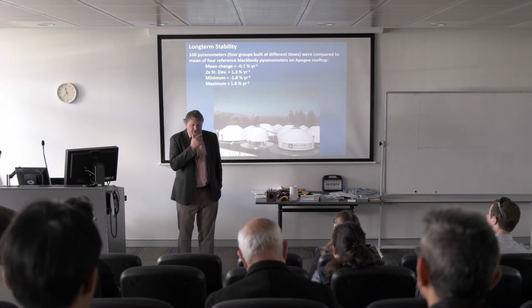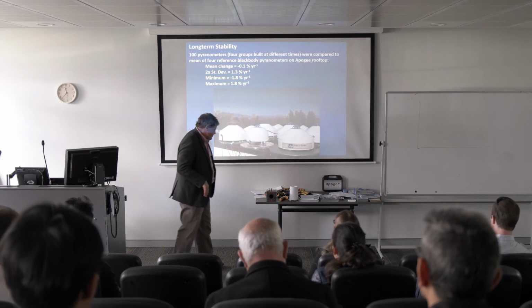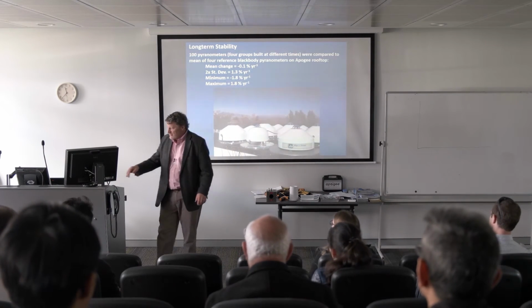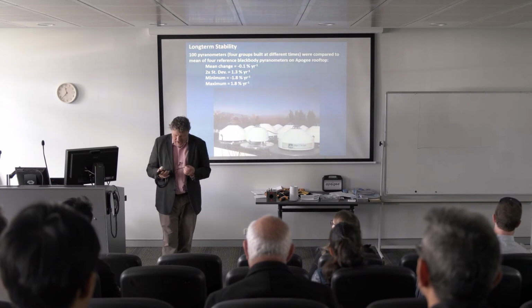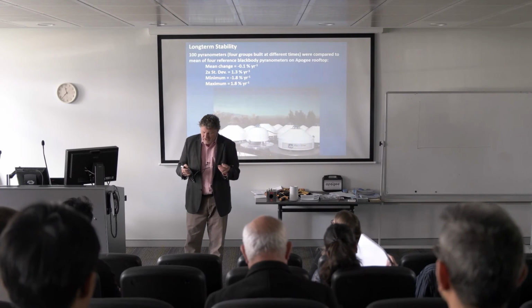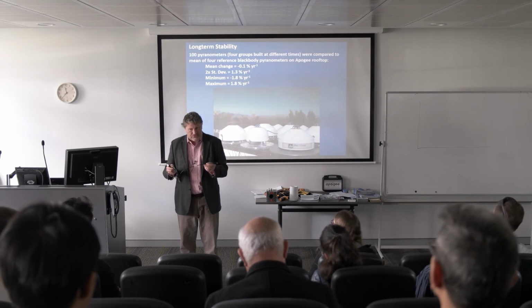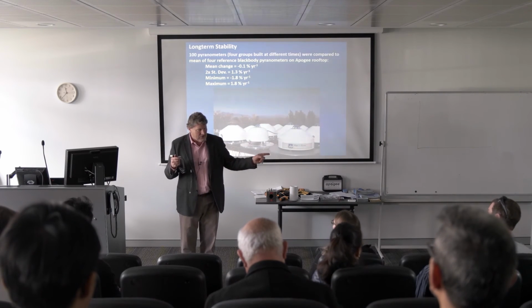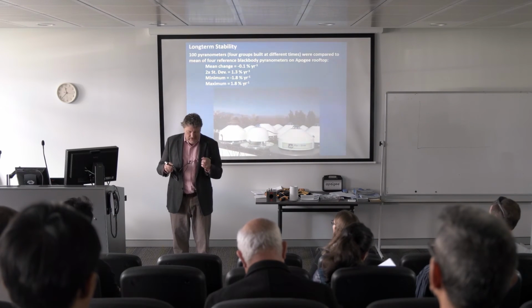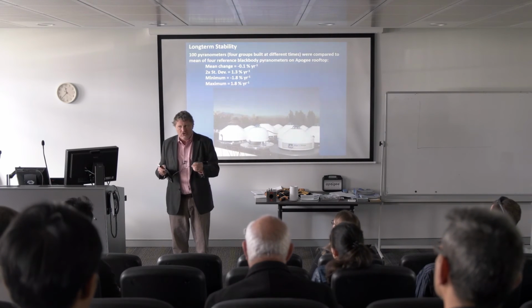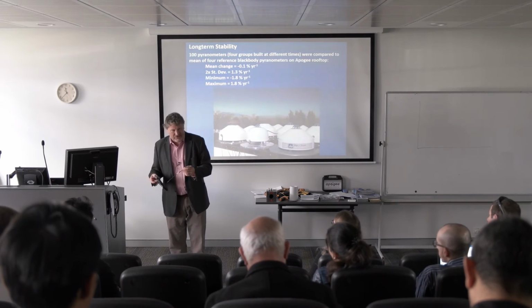I want to say one other thing that's not on the list, but I'll use this sensor as an example. The cable leading to sensors: different companies use different cables. You've got to get the signal from the sensor to the data logger, and higher quality sensors have higher quality cables coming out of them.